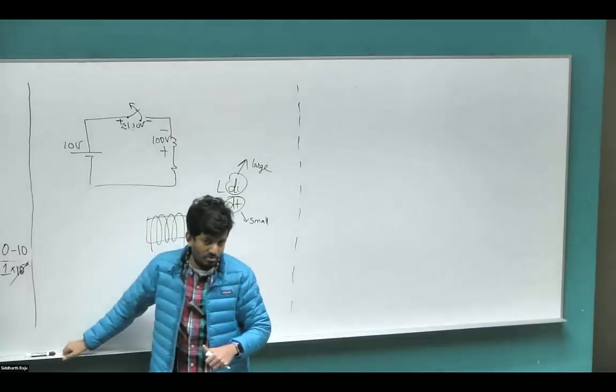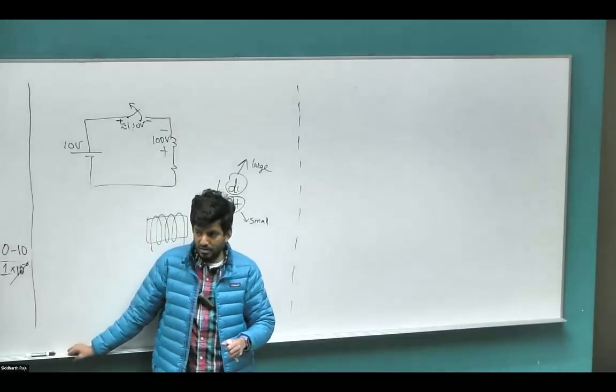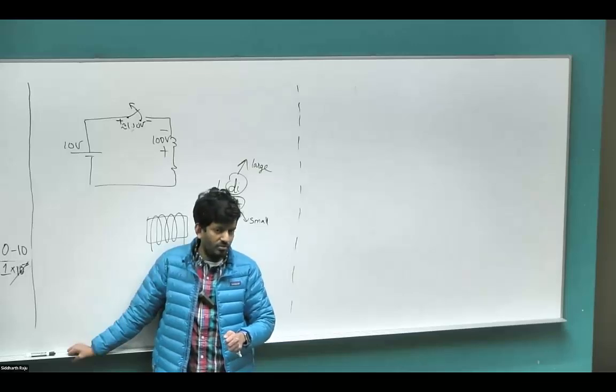What are all the possible solutions? Yep, Ben. You run a flyback diode that's normally reverse biased. Right, perfect. Any other answers? Is this the only solution? We don't want to take any other guesses?